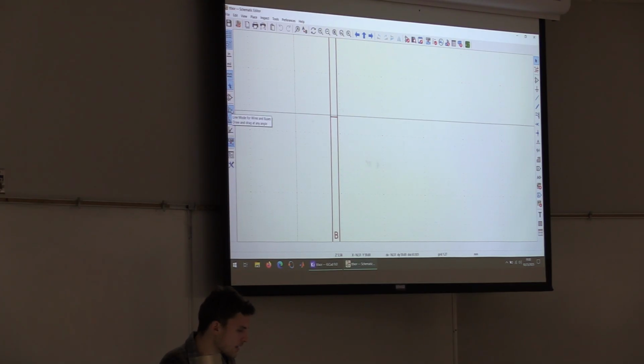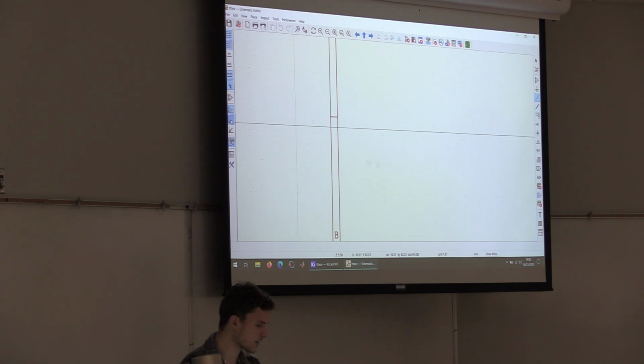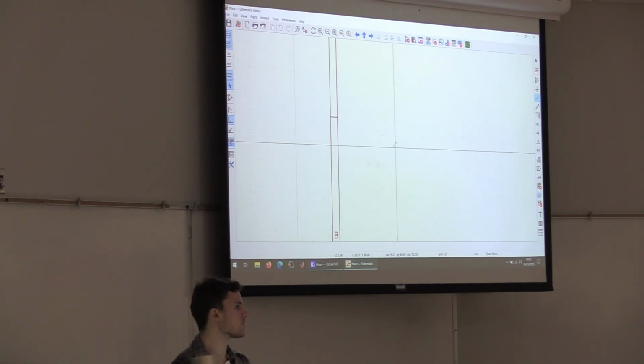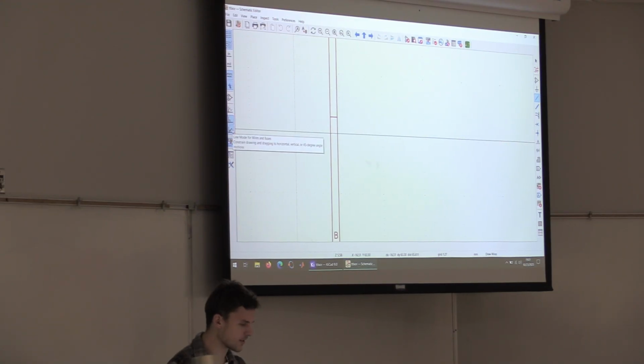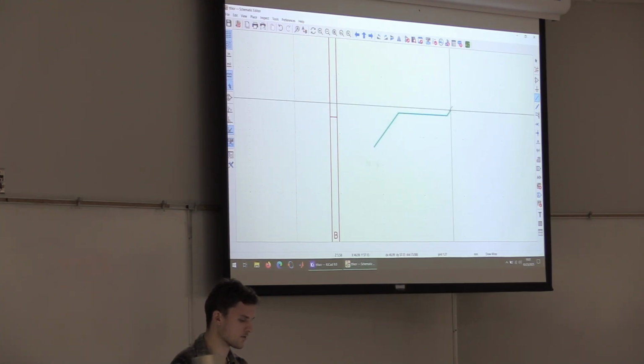We've got our different line modes. This one would be a free draw kind of thing, while this one limits to 90-degree angles only. I typically keep it on that, but sometimes you'll have a design where you want to have an angled wire. With schematic design, we try and keep it 90-degree, but to each their own. And then this one is for 45-degree cases, so maybe you'll have some sort of crossed wire design.